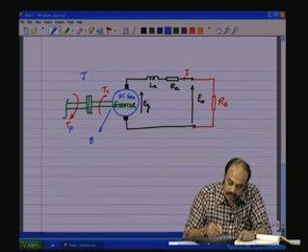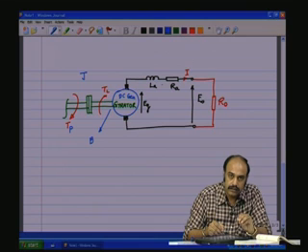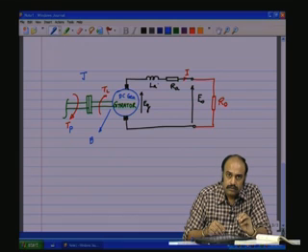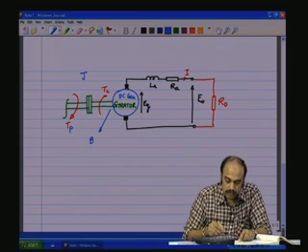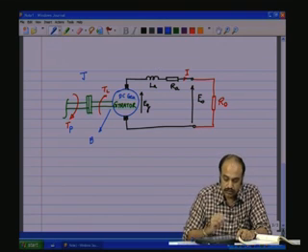On the electrical side we have LA, the armature reactance, which is represented as an inductance LA, called the armature inductance, which we use for the dynamic model. In the steady state model, that does not come into the picture because DC currents are flowing and the induced voltage is 0 there, and RA is the armature winding resistance.